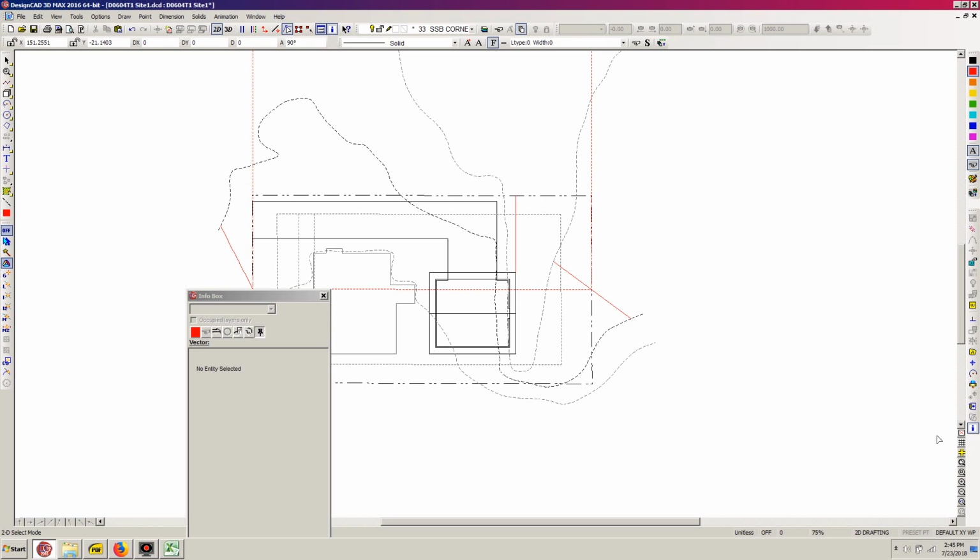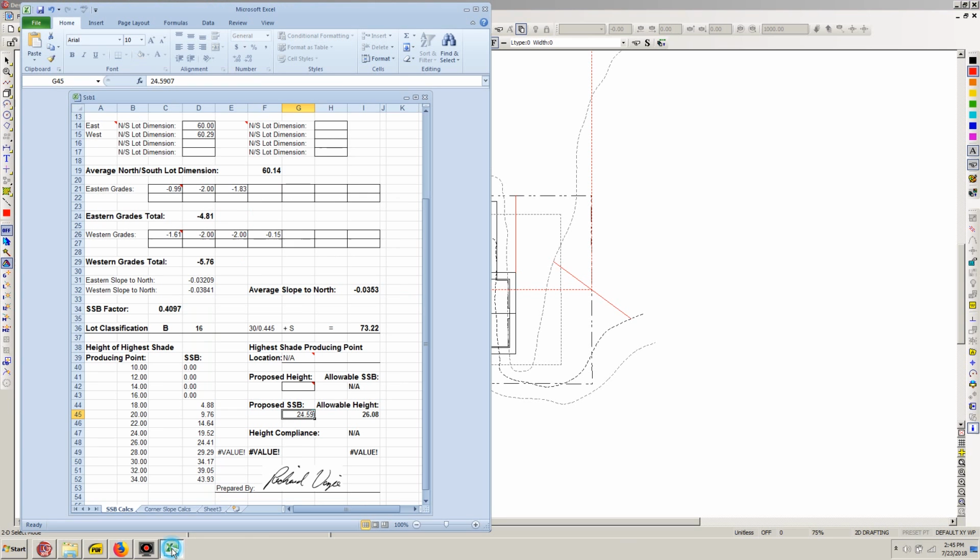But we know that the main garage floor is 8 feet. You can figure on the floor framing to be at least a foot, so that's 9 feet, and then another 8 feet for the additional floor. So that's basically 17 feet. So probably by the time we get down the grade, we might be 18 or 19 feet high.